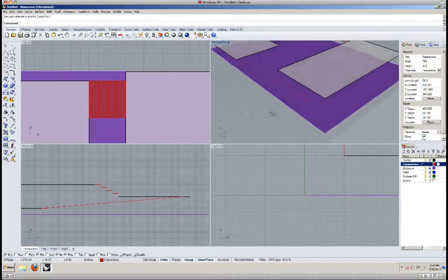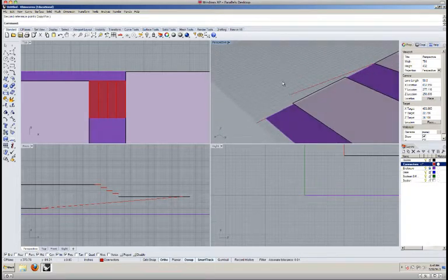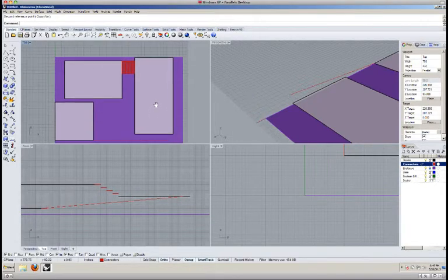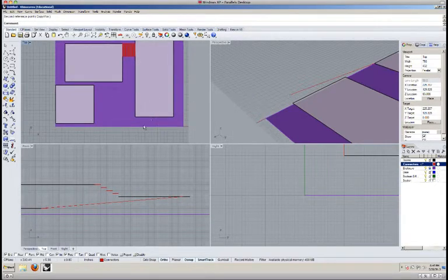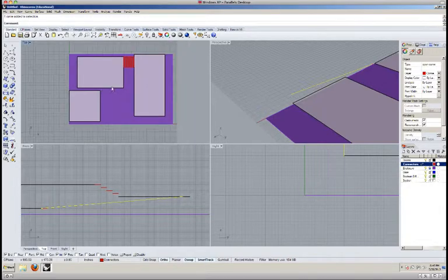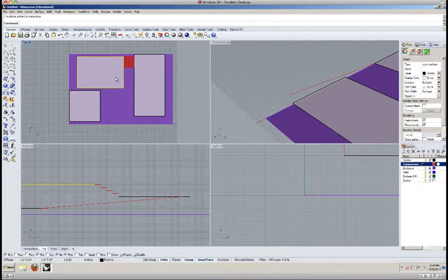So you can see that our ramp is going to extend over here this far. I might at this point want to do some adjustment to the way that I have organized my project, or organized my spaces. I know that the width of this ramp needs to be 4 feet, and it's not quite fitting here, so you could either reorganize so that the narrower volume is rotated 90 degrees from where it's showing now, but then you'd have problems with the longer one fitting. These are design decisions that you'll need to take into consideration.